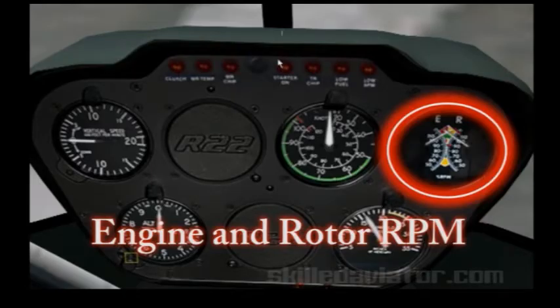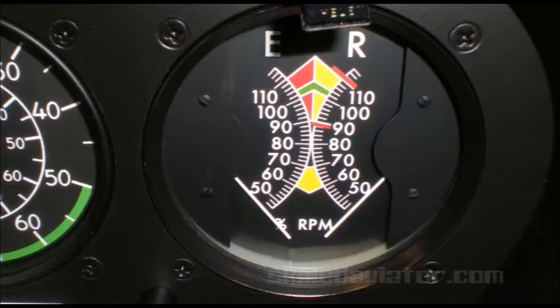The instrument on the far top right indicates both the engine RPM and the rotor RPM. This instrument has two needles, one for the engine marked E, the other for the main rotor marked R. In normal flight, the needles will indicate the same value and they are marked in a percent as opposed to a specific RPM. There are also colour markings on this style. Again, green is good, red is bad, and yellow is operated with caution.